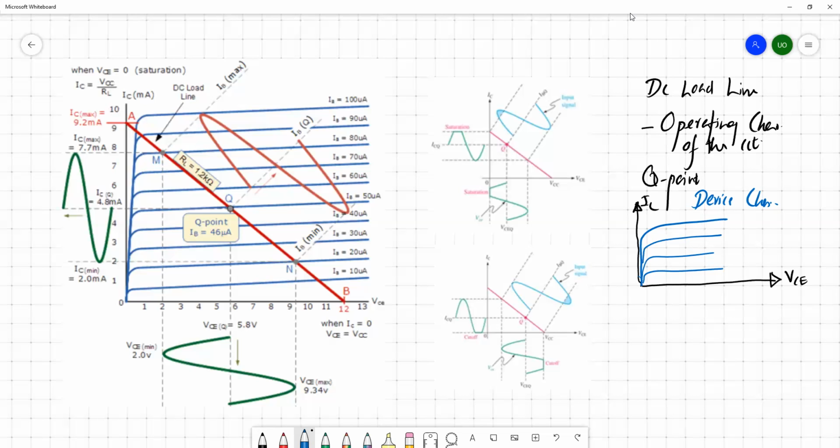This is normally analyzed numerically in a circuit analysis tool, but here we can simply use that concept. Capacitors and inductors are replaced with open circuit and short circuit elements, and you simplify the circuit to the DC equivalent circuit.